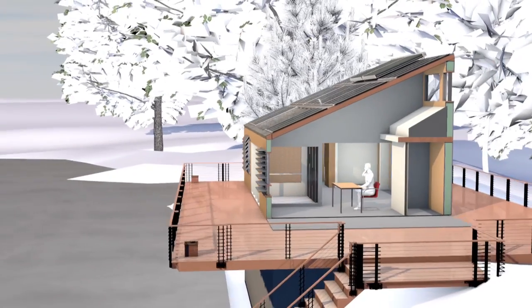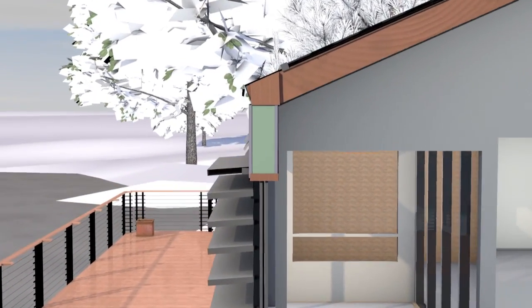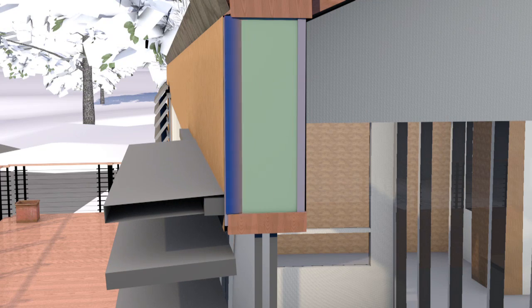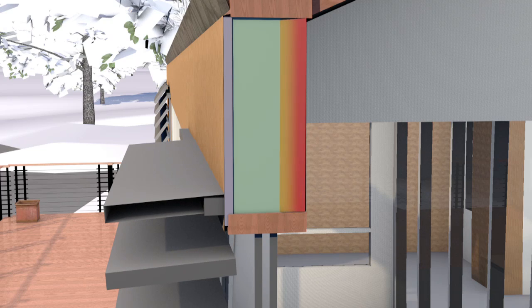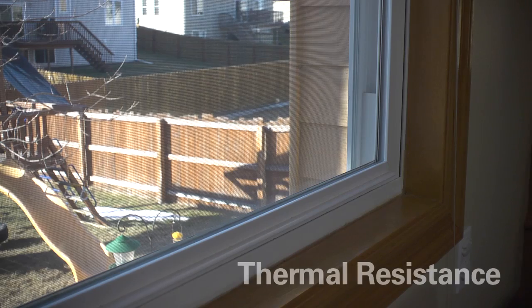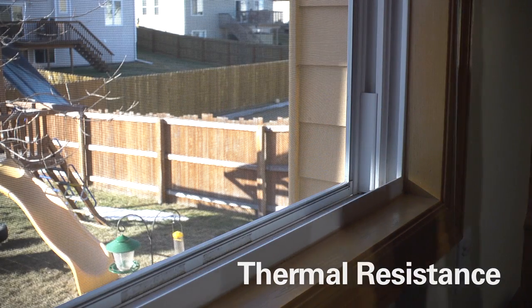Our building shell is a kind of thermal media. Heat from indoors is conducted through the shell to the outside in winter. If we look inside the building shell, there is insulation inside the wall, and we have an inert gas inside the double-layer window. The insulation and inert gas can increase the thermal resistance of building materials. The thermal resistance is the resistance of materials to the flow of heat by conduction.